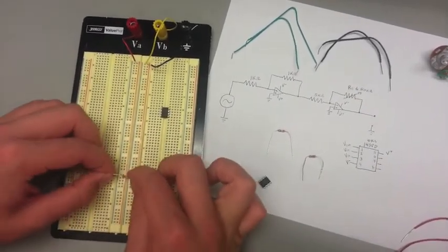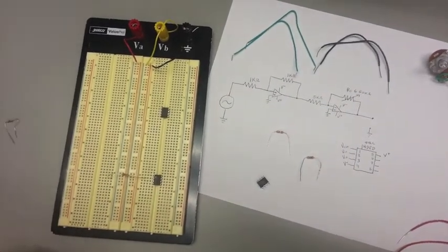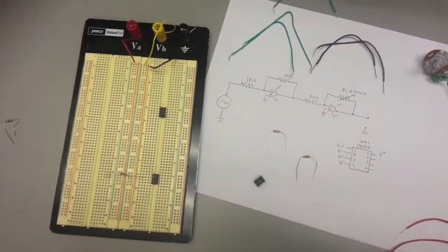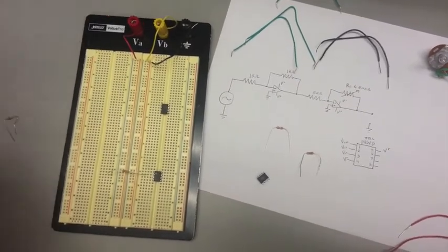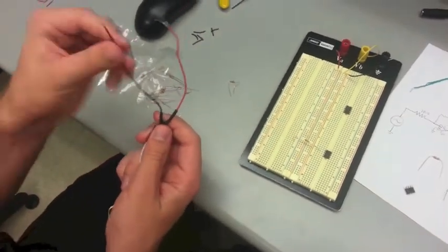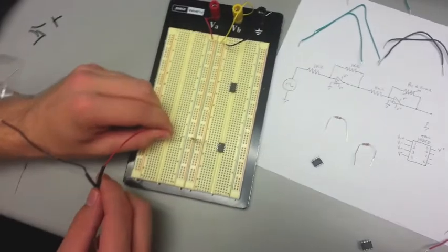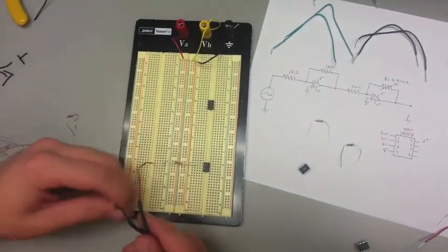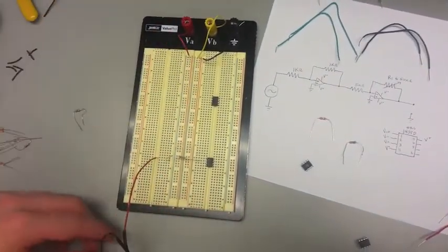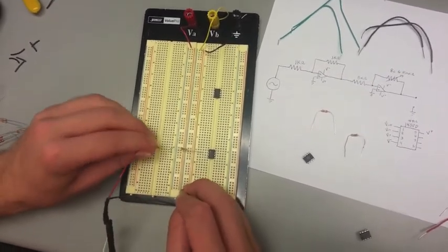And so you'll put the resistor right here. Actually, we don't need this wire. We can just directly put the input cable right here. You see the white wire, for our purposes, we will not use. The black wire goes to ground, and the red wire is the input. You put it in the same row as the resistor, and then you put this row into the black column, which would be the far right. So this is now grounded, and we now have an input.